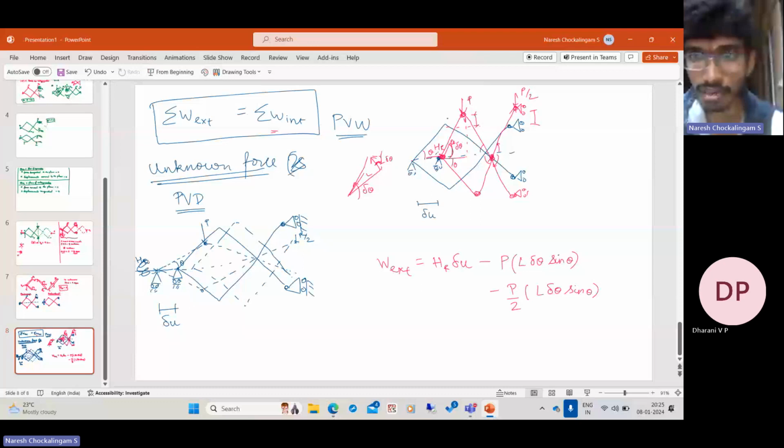If you have an assembly of components and subject it to loading, it has to deform, generate internal forces, and resist the applied force. When it is a mechanism, it accelerates. It cannot deform. So when it doesn't deform, by Hooke's law, there is no stress, so there is no internal force. And if there are no internal forces, the internal virtual work is zero.